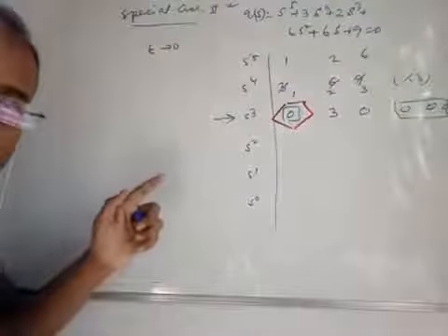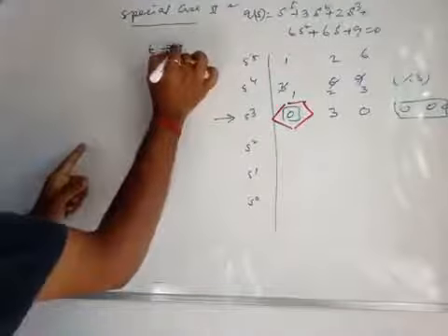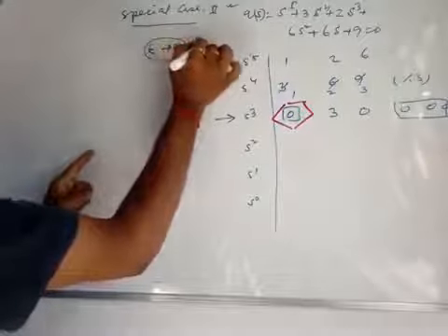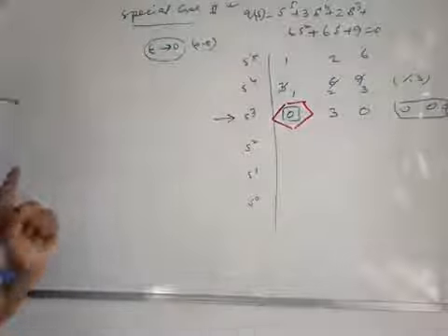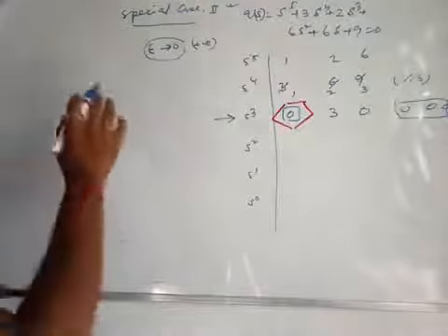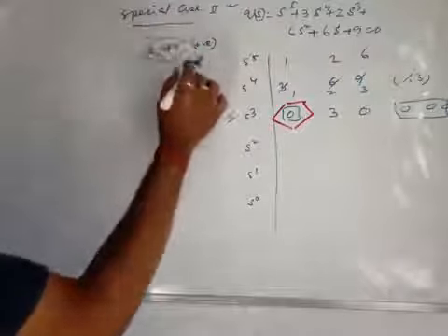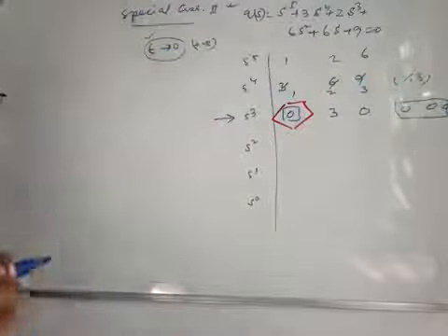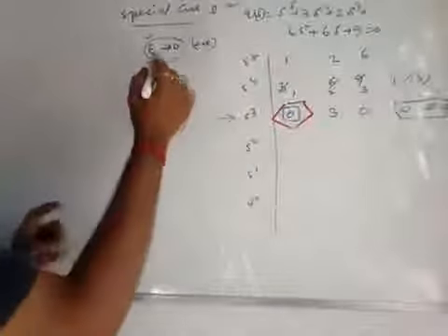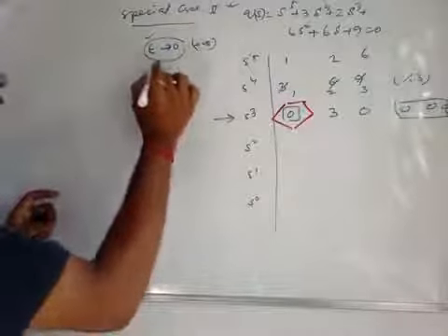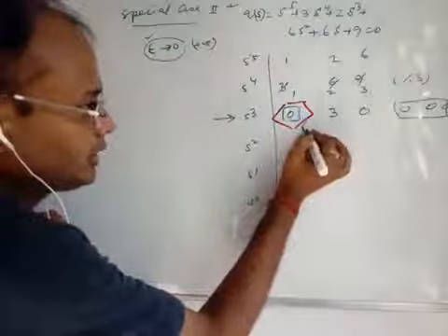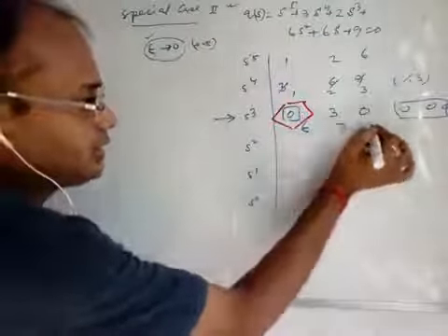And see, if epsilon is a very small quantity greater than 0 and tends to 0, that is positive, but it may be negative also. But here, for the Routh array consideration, this very small quantity epsilon is taken to tend to 0, and it is taken to be a positive value, right? So once this is a finite value very close to 0, we will just bypass this value with the small term epsilon, and this is 3, this is 0.